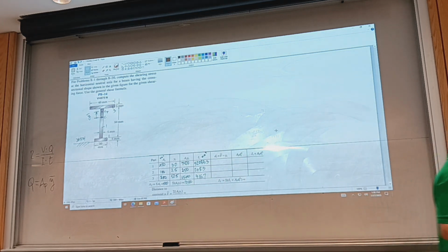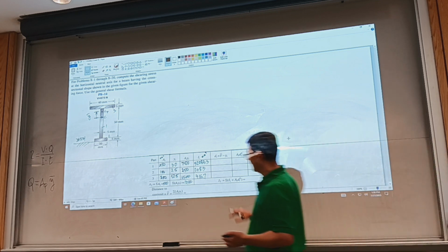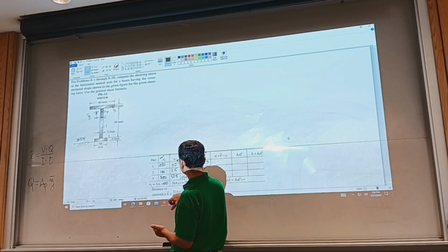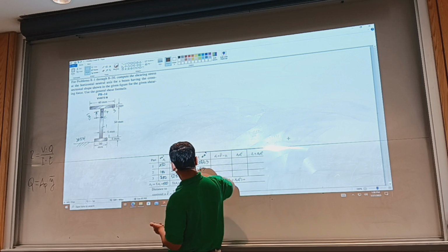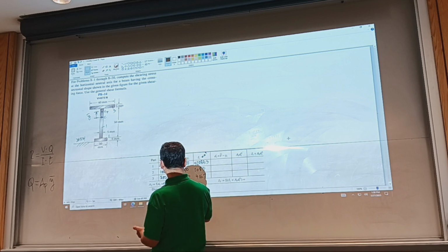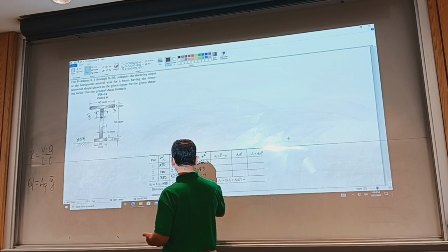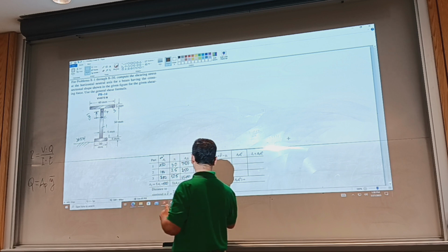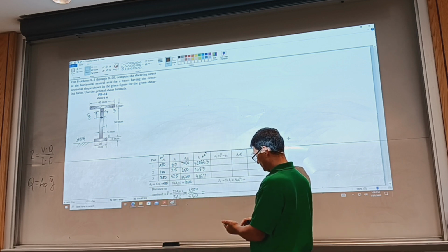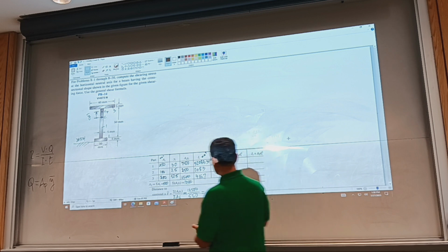I think I took this outside of the viewing area. So I cropped this off, it's out. So it'll be what? It's the sum of A times y over the sum of A. So over sum of A, and this is 12500 over 550. Okay, 12500 over 550. This is 22.73.